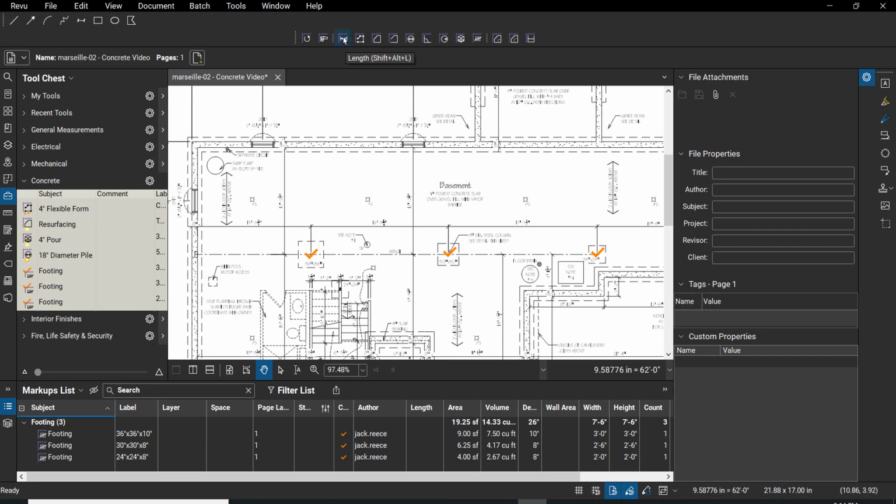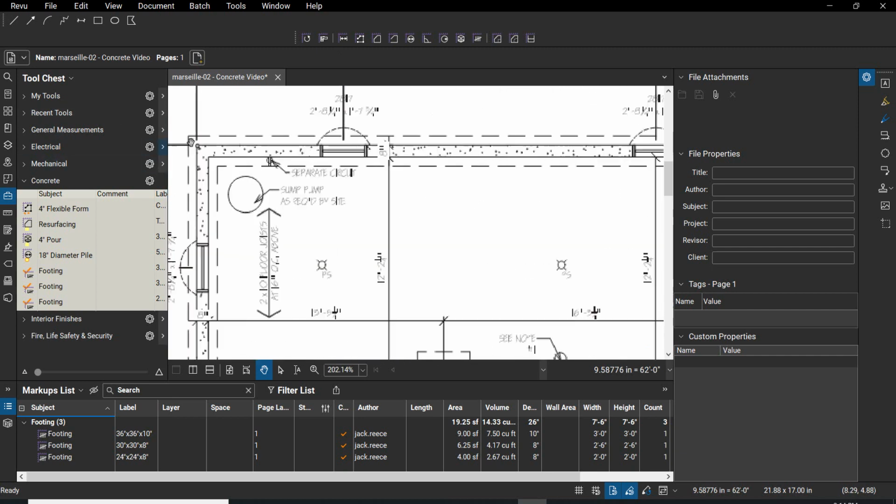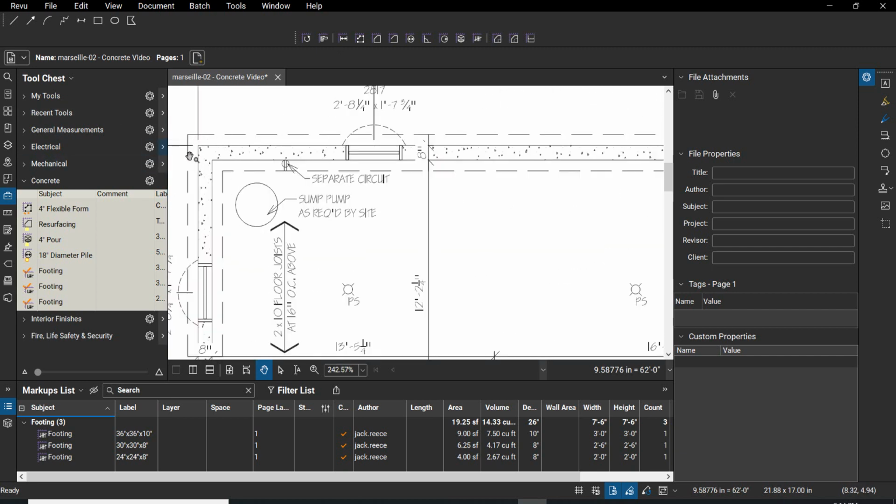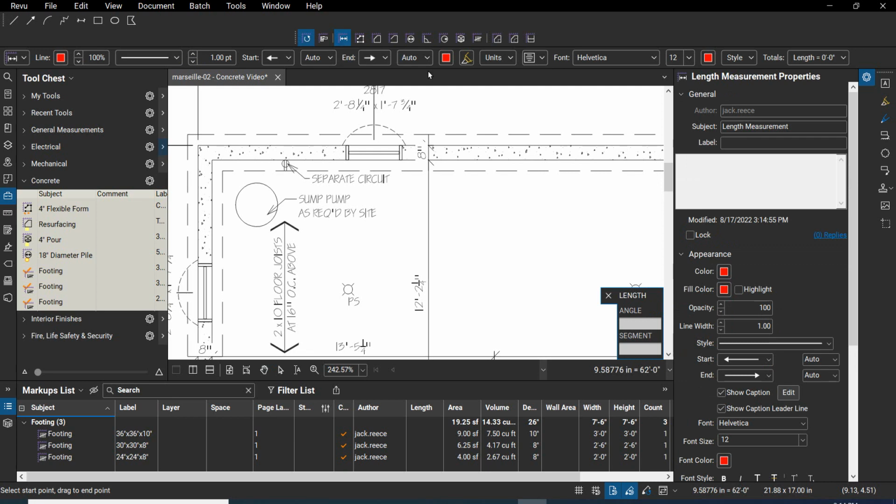And so let's come up here and go. You could do lengths, you could do poly length. Okay, I've seen it done both ways in some research I've done. And I think our length measurement is going to be our best way, because we don't want to duplicate corners of our takeoff. Just like when we're doing it by hand, we don't want to count this square in the corner intersection twice. So let's just go with a length takeoff.